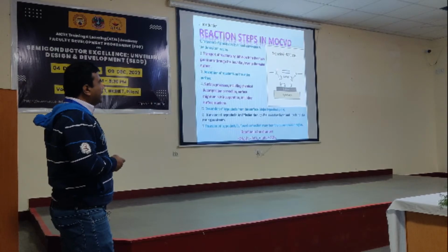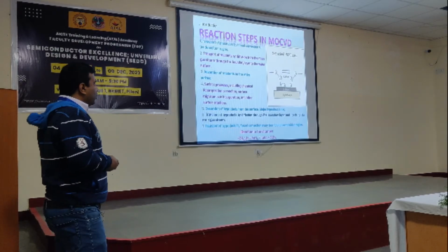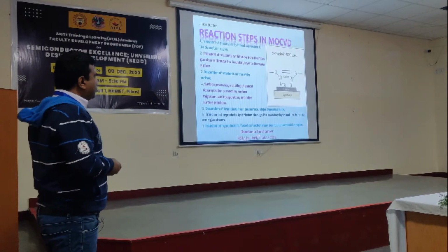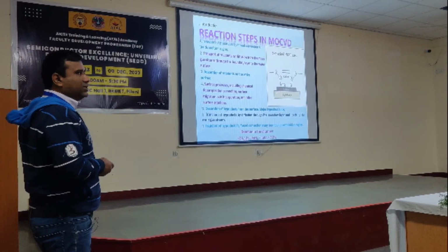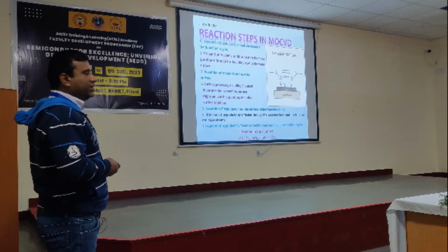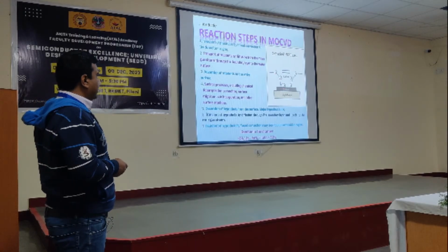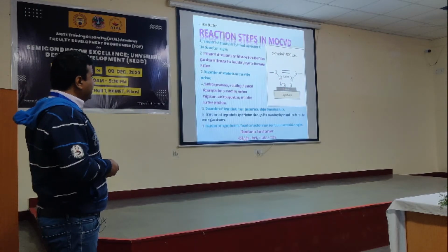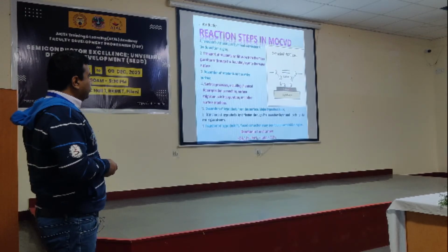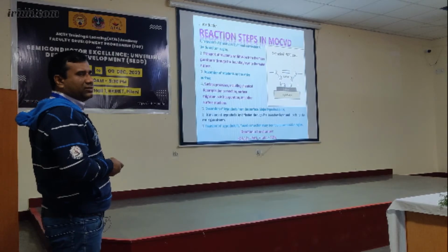Now CVD. CVD is nothing but the chemical vapor deposition technique. All the chemical materials, including arsine, will be transported into the reaction chamber by a suitable carrier gas, which in your case is hydrogen. So hydrogen will carry this one and this one into the reaction chamber. The reaction will take place. Indium will combine with arsenic, and another byproduct is methane that is vented out to the scrubber system.